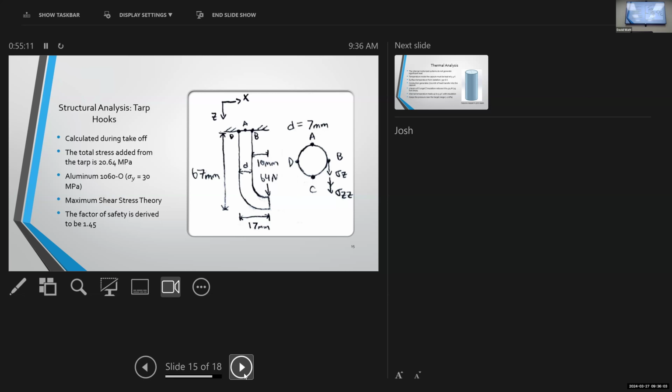First, we normally don't use 1000 series for structure. Yeah, annealed aluminum is nice and soft, right? If you can get something like 6061 or 7075, tempered and higher strength, you're going to be able to optimize the structure, because they're the same density and one is stronger.